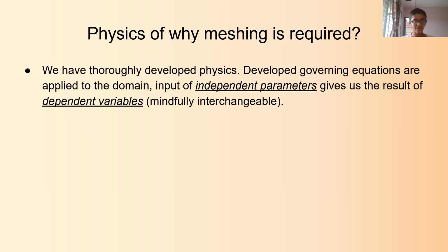In stress and strains also, we have principal strain, Mises strains, and we have directional strains, Tresca criteria, invariants of strain, shear stress. So there are a lot of different sets of results we can have.